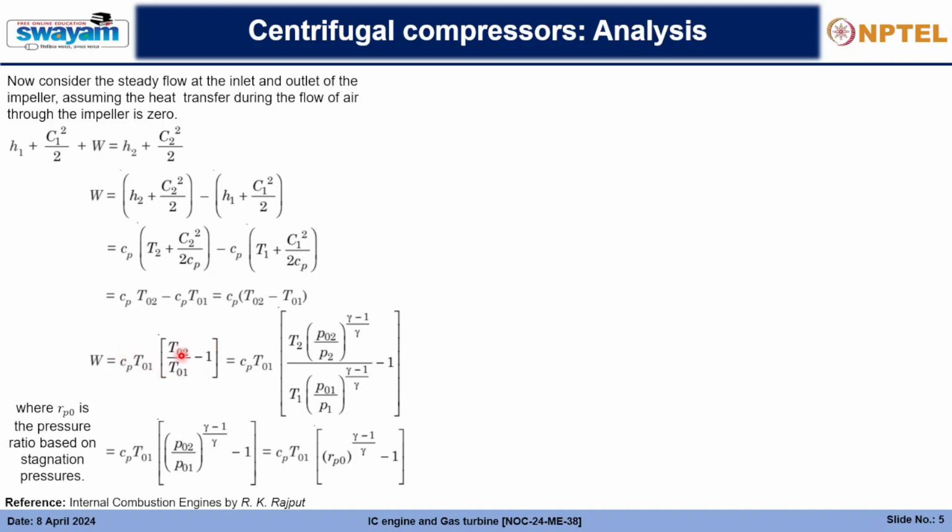We take common T01 and that is the initial condition. That's why we take common the initial condition, and from that we will have the value of T02 to be equal to T2 into P02 by P2 whole to the power gamma minus 1. Yes, we can write that because that is the isentropic condition. So from an isentropic process, we can write that, and also similarly for the case of 1 here.